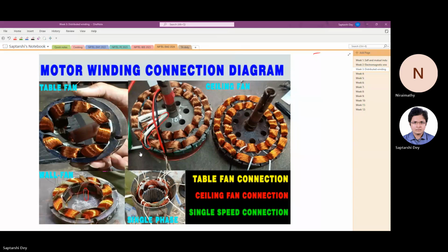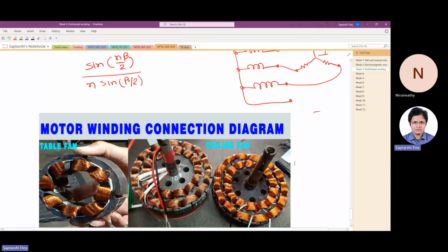And what may be the insulation level? It depends on the voltage level, 1 kV, or it may be simple enamel. There are classes of insulators now. I do not remember what is required for what. The voltage level and the operating temperature that you need decides that. Turn to turn voltage and operating temperature. Okay, sir, thanks a lot. If you see classes of insulations, you will get that. Or you can see some machine design book, they can have a chart, and some handbook may help.